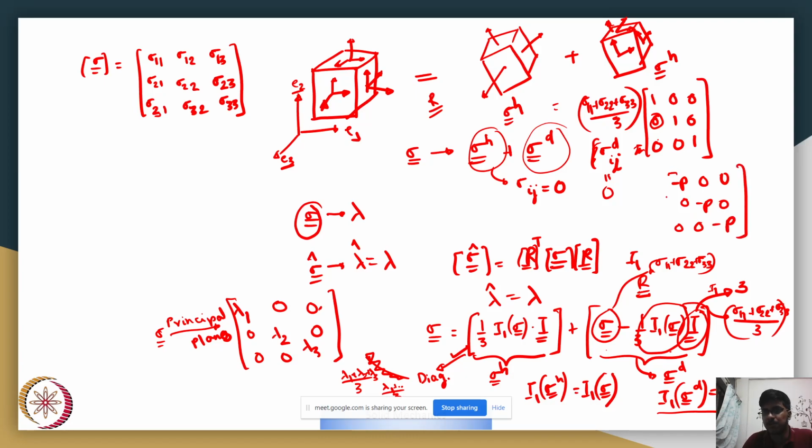For fluids, this will be only compressive, but for solids, this value can also be positive. So you can have a uniform elongation in all three axes. Whereas this other part, the deviatoric part, essentially causes only shear. So you essentially get a distortion of the cuboid. One will increase or decrease the size of the cuboid, the other might make it into a parallelepiped.